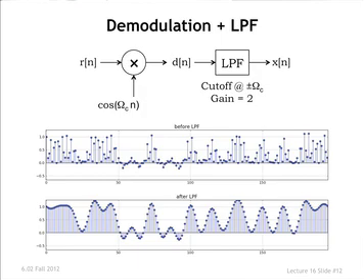Okay, so this is the picture that we have at demodulation. Sorry, this is not well drawn. That shouldn't be x of n. That should be the received signal. So the received signal comes in, gets multiplied locally by a cosine, gives you the demodulated signal, and then you have the low-pass filter. So I'll change that before I post it.